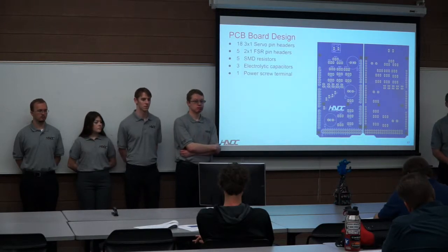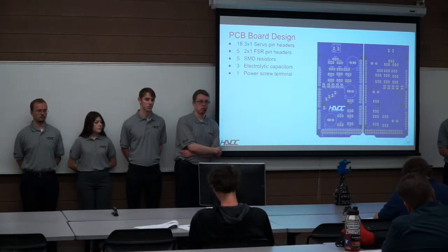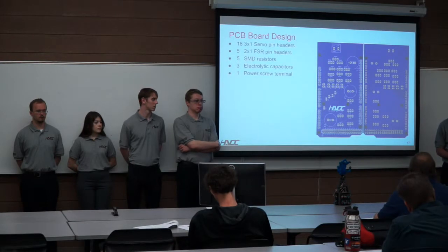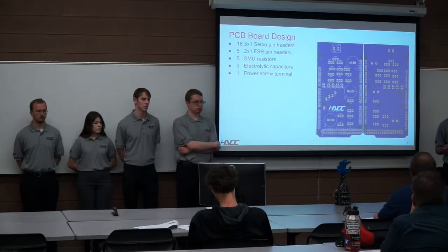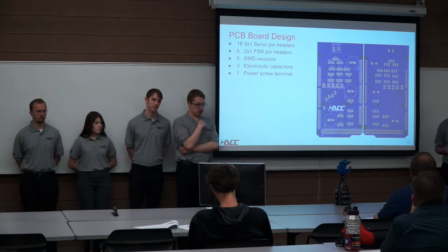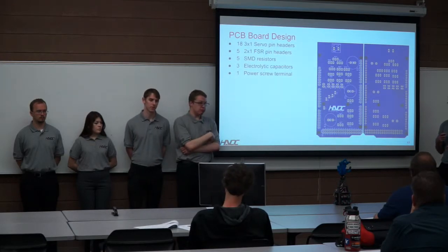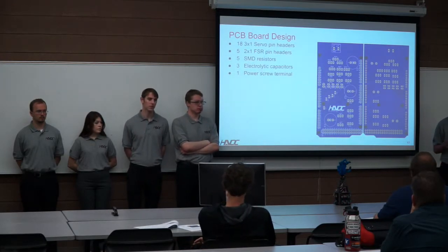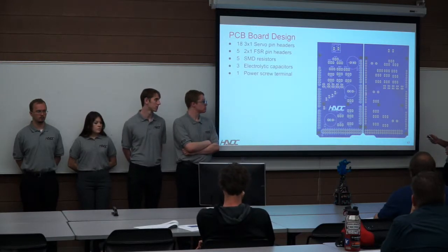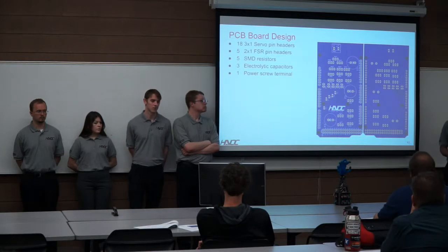We had to print this board from Park instead of in-house because the in-house boards do not have through-hole connections, which means we cannot only solder on one side. We need to be able to solder on both the top and bottom, because we have some tracings here that have connections on both the top and bottom.